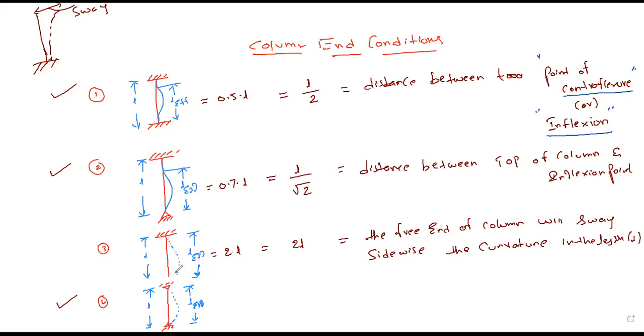So this is only half of the curvature. The other half of the curvature will be similar on the upper half of the simple column, right? So by that, the curvature in the length will be considered on other half of the column. Okay, so that's the reason why. So your effective length is 2 times of the L output.